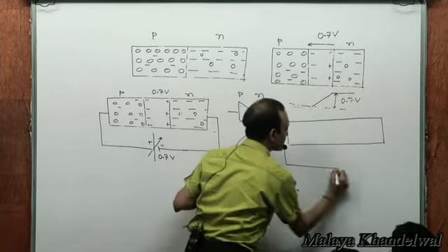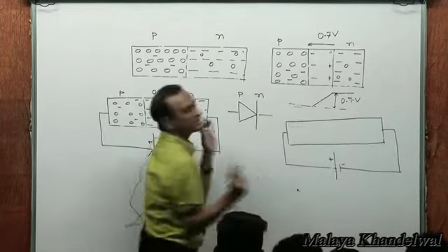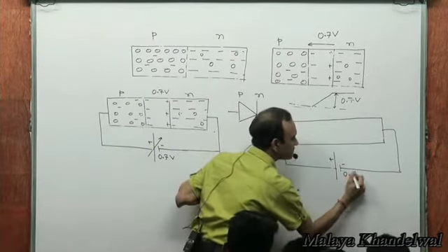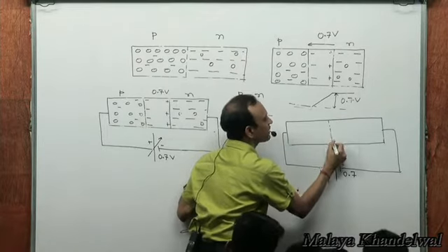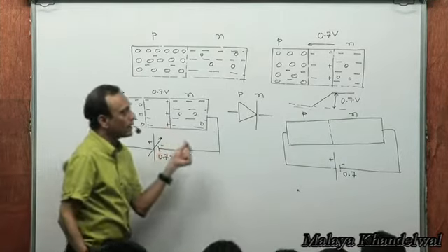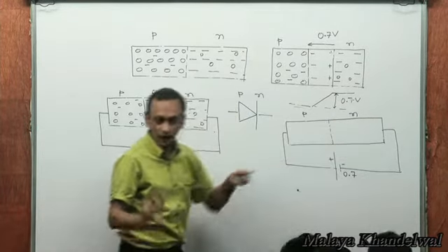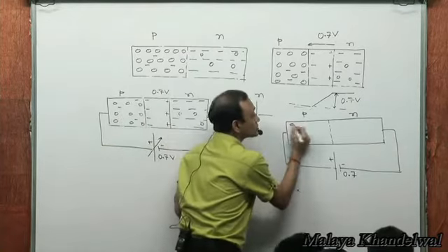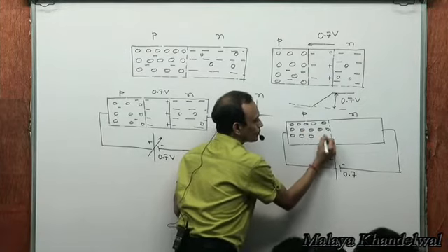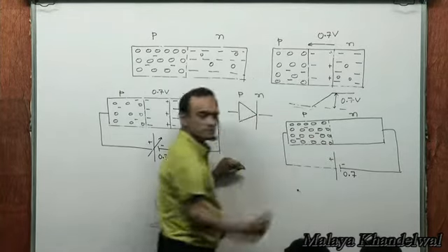The moment this becomes 0.7 volts, and this is 0.7 for silicon, so it depends on what semiconductor I'm using in principle. So when this is 0.7, the depletion layer that you saw there vanished. It shrunk to 0, right? The holes here had enough energy to get passed on to the n-type. Clear now? So now I have, say, holes here, and minority charge carriers electrons here.